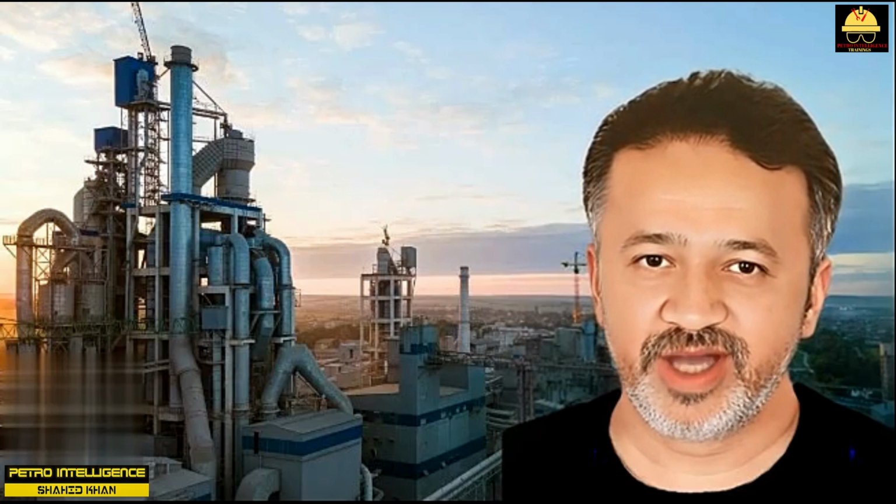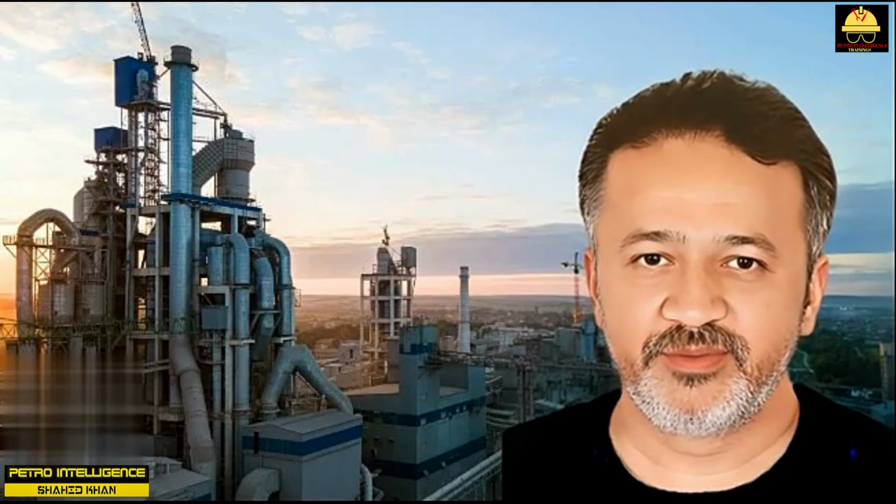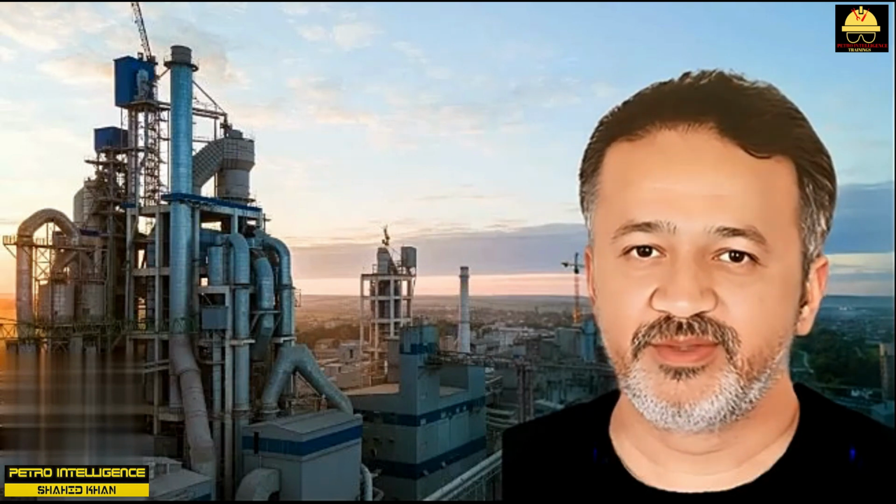I've read about the importance of shell side cross-flow in heat exchanger design books. Higher cross-flow velocities reduce film resistance and promote increased heat transfer rates. Recently, an engineer had a dramatic personal experience to support this engineering principle. A refinery had a debutanizer reboiler with an observed heat transfer coefficient of 25 BTU per hour per square foot per degree F. The reboiler was a horizontal, thermosiphon, shell and tube exchanger. The heating medium was 400 psig steam on the tube side. Except for a short length of the tubes, the shell side flow was parallel to the tubes.